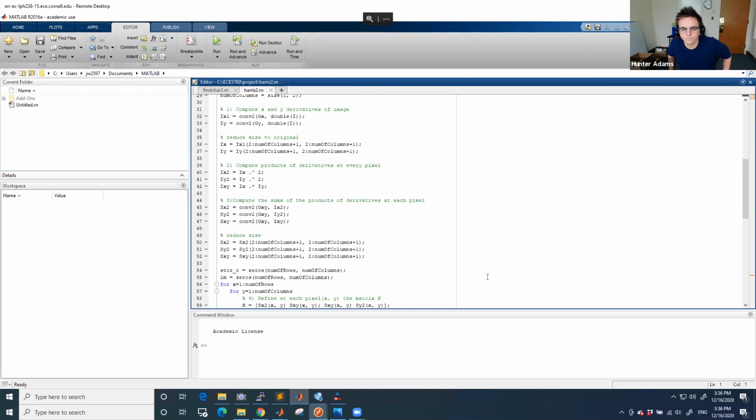Okay. So we combine them, and we don't have to worry about the flipping or the derivative step that Hao mentioned. If we want to take the derivative along X of the image, we would have to use another kernel to calculate the pixels before and after it. But because the Gaussian kernel is just 3 by 3, we can calculate by hand the derivative of the Gaussian and store it in a 3 by 3 kernel, which is in the FPGA. Okay.